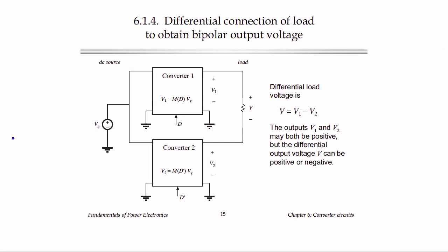We saw in the last lecture how to apply transformations such as inversion of source and load or a cascade connection of converters to take a DC-DC converter and generate a new DC-DC converter that has different, possibly desirable properties. The approaches that were considered in that lecture will not generate an inverter. So suppose we have DC-DC converters, but we want to make a DC to AC or AC to DC type converter. We need to be able to change the polarity of the voltage, and so far in the previous lecture none of those approaches would accomplish that.